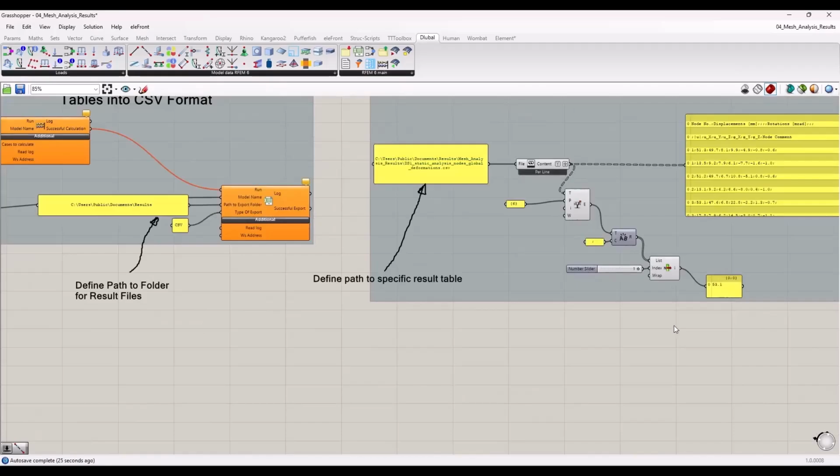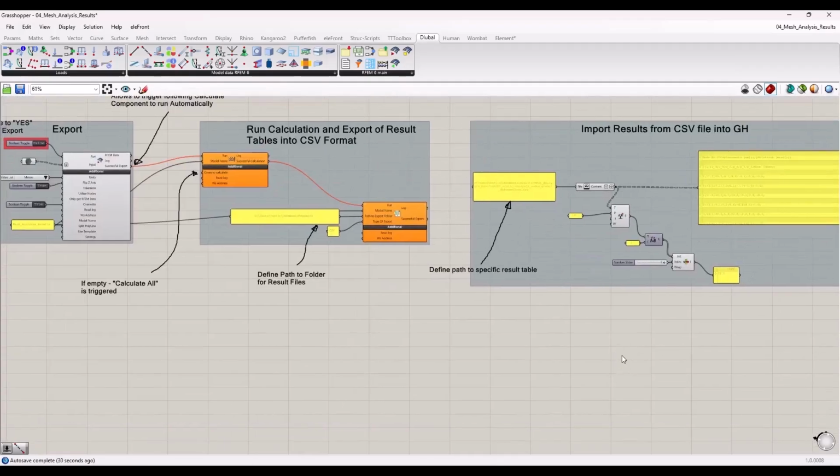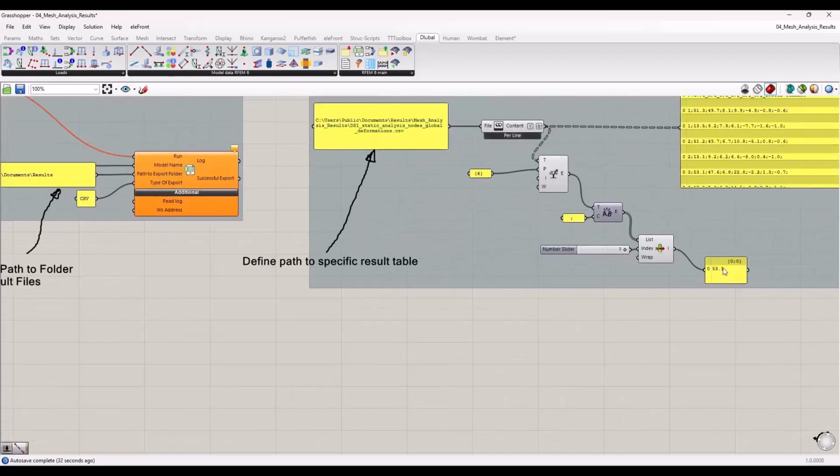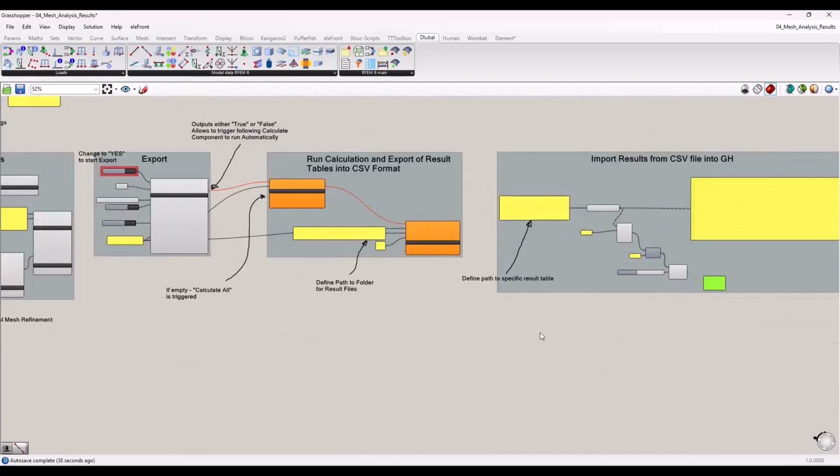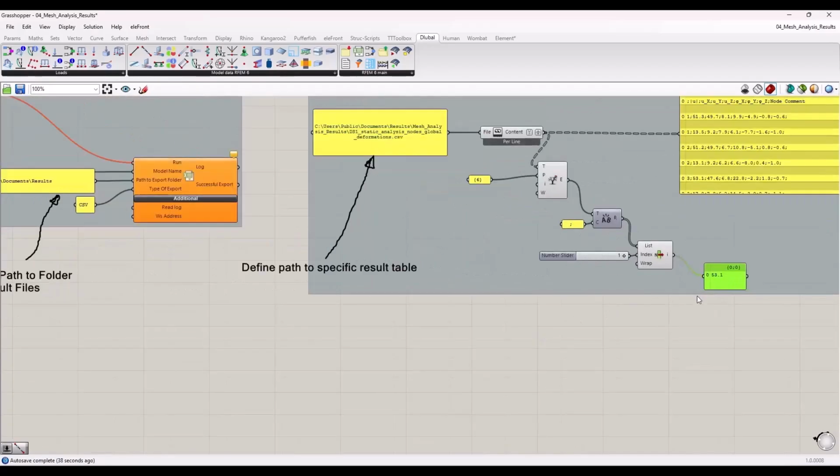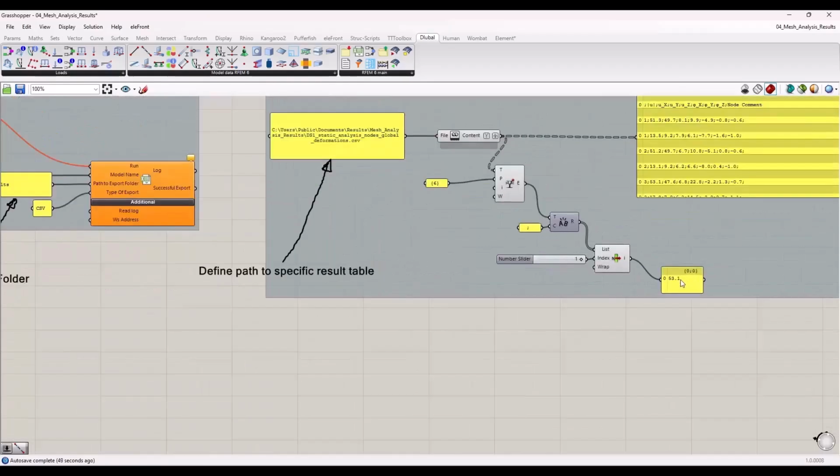You could think about additional features now. You might say, okay, hey, if I have a result in Grasshopper, I could maybe use additional plugins like Galapagos to run calculation loops. I showed that in a different webinar briefly as well, but that is also possible. Yeah, you could say this is the target value which you want to optimize.